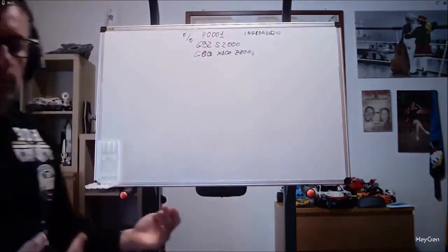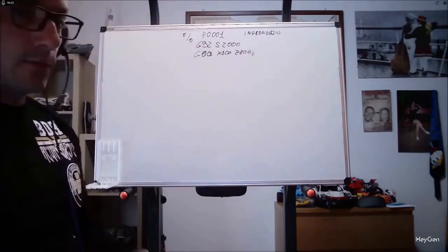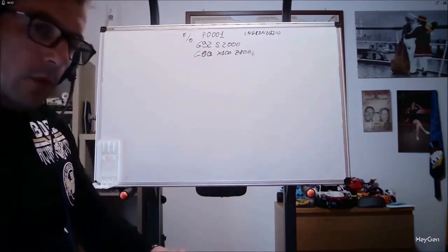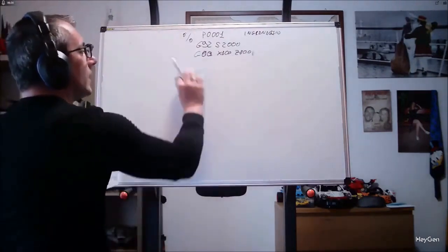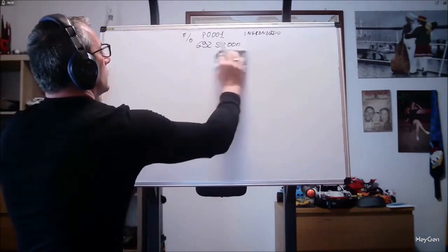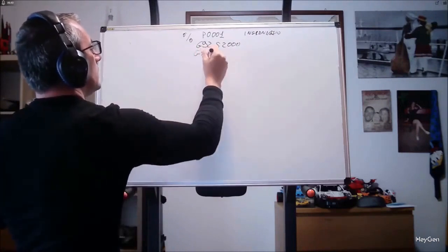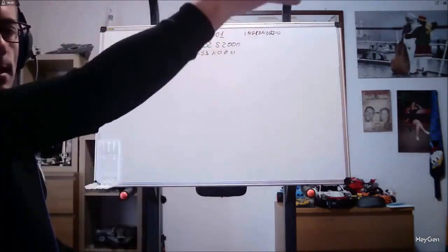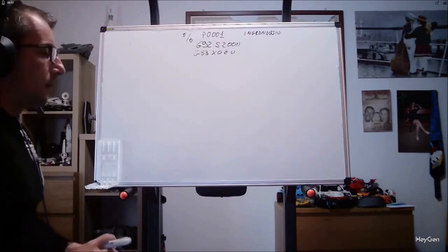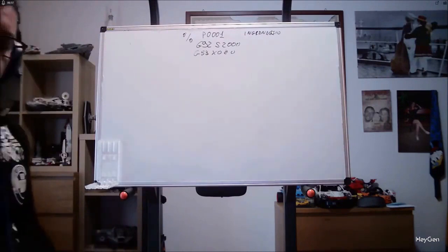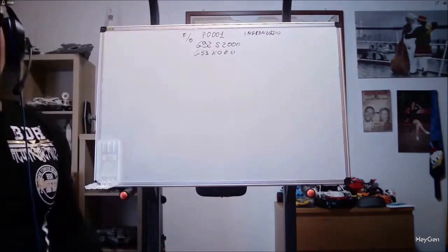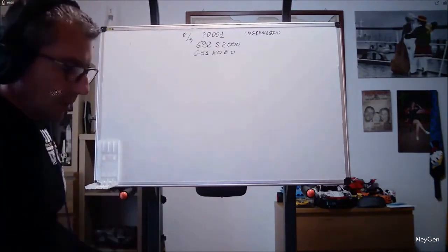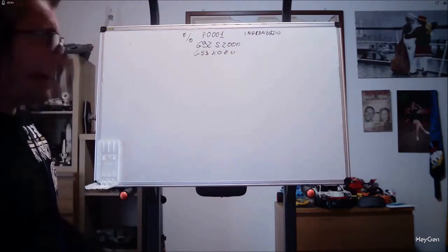I foresee an approach to the first movement block, first in Z and then in X. I will explain this too. I don't define this as important, but know that if you find it, especially on Fanuc, I remember this well. G53, X0, Z0 tells the machine to go to its origin point, which is usually high and far from the spindle. After that, we need to start thinking about calling the tool we will work with at the beginning of our piece. So here we have a bit of variation.